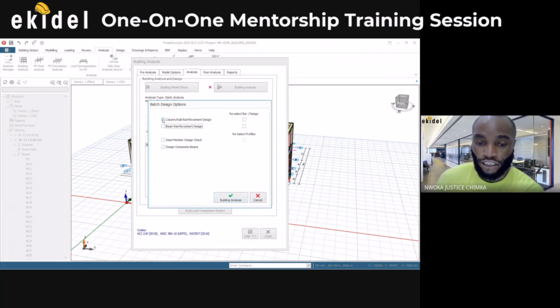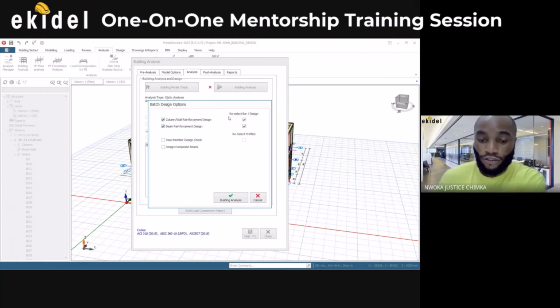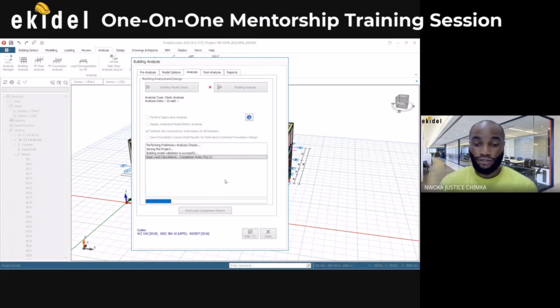I'll check design and also select bar. So I'm saying that if the 16 that we chose before for the minimum is not sufficient, it will jump to the higher one. That's what checking this does. Then I'll click on Building Analysis here and wait for it to begin.